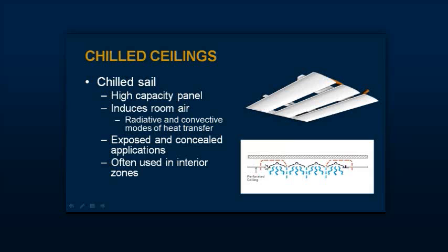Now, this is my conference room, and I have to admit I'm quite proud of this room because I've been playing with the functionality of this room. But the original reason that I put sails in this room came from thermal complaints from our own people. This room was designed originally with this odd shape in the ceiling with that curved linear around it as a way to highlight the fact that we could curve these linears. We also had 1,000 CFM air going inside this space to cool it, and direct south-facing windows, and we had a lot of radiant problems inside this space.